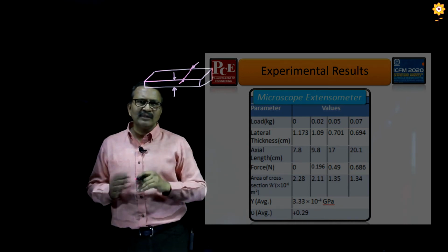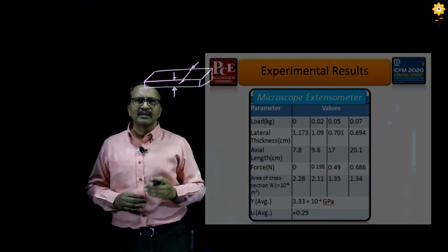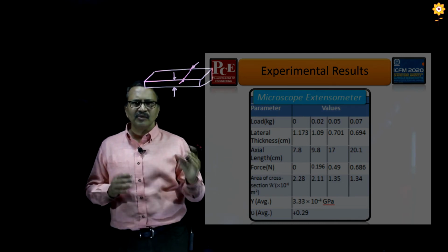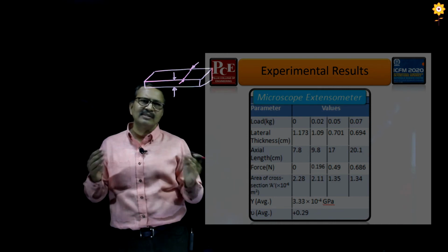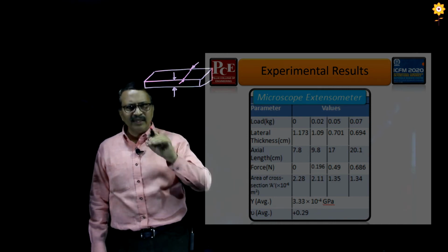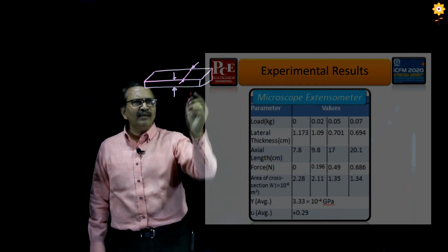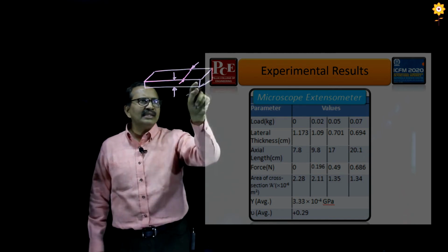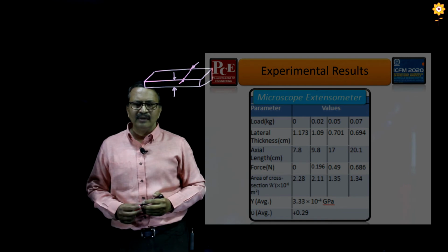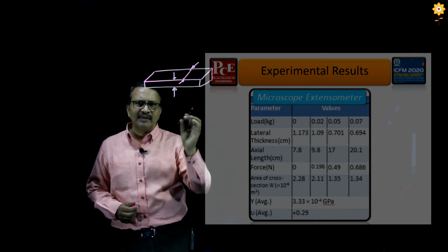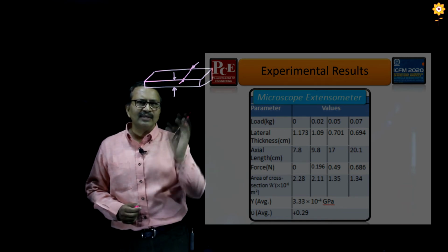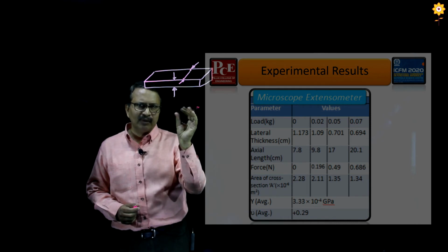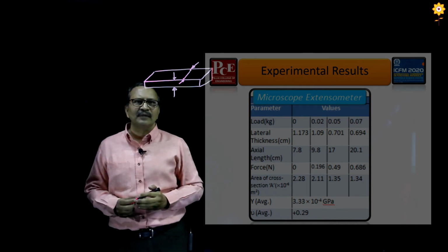And mind you, we got this idea after studying the video extensometer that we have seen in the industry. In the same way, instead of using a spray, we simply marked this, and this length is of course 1 centimeter, and then using the microscope we tried to find out by how much it has compressed, because in this particular case it will compress as I am stretching it.